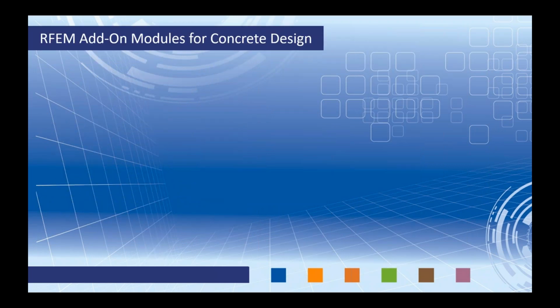To begin with, RFEM is our main program. This allows us to fully model and load the structure. We can create load combinations according to the ASCE 7, NBC standard, and run a full analysis. With the analysis, we're going to get things like internal forces and deflections, and we can take those in, as I mentioned before, into our own in-house tools to do the reinforcement design.